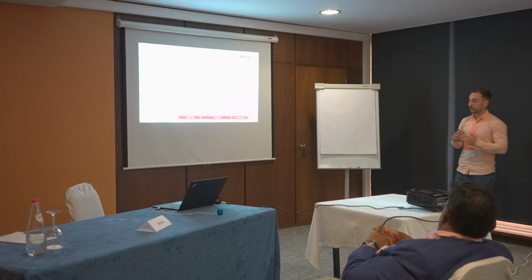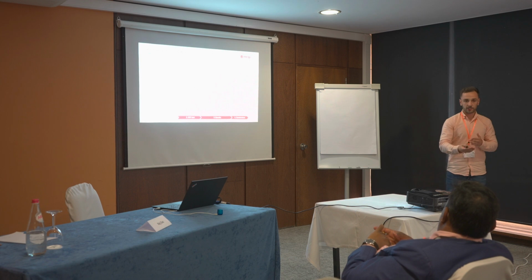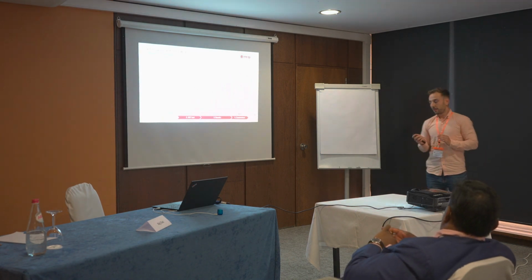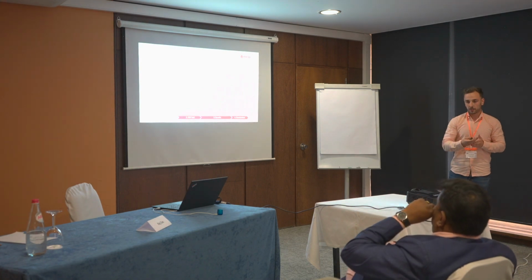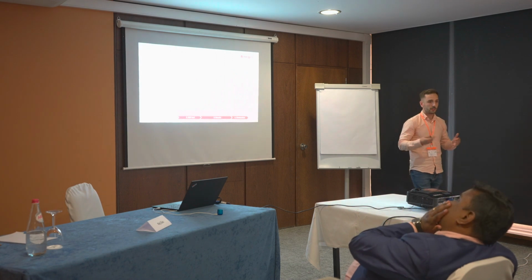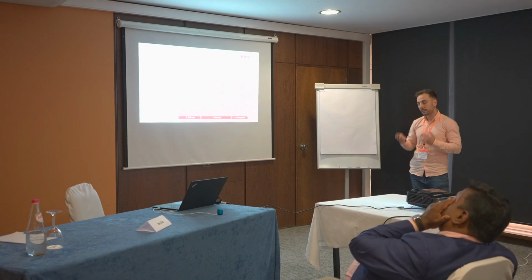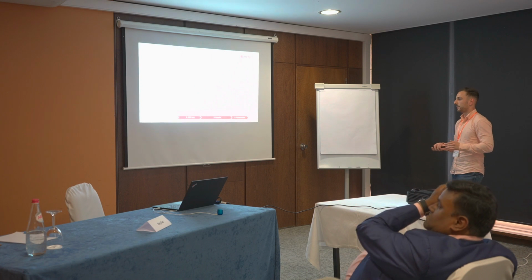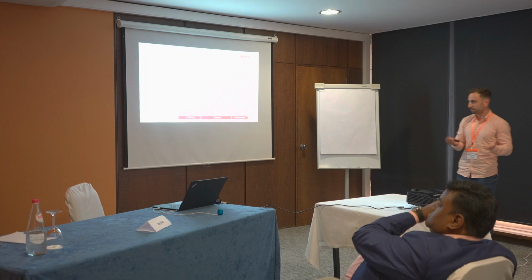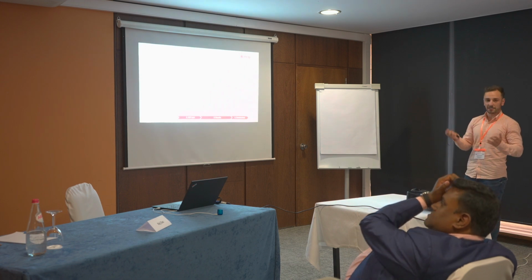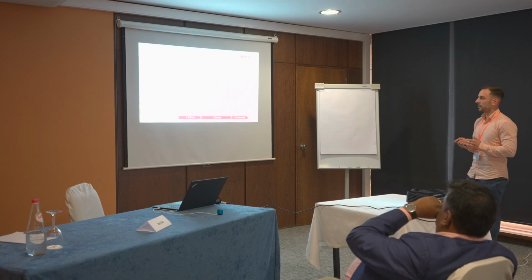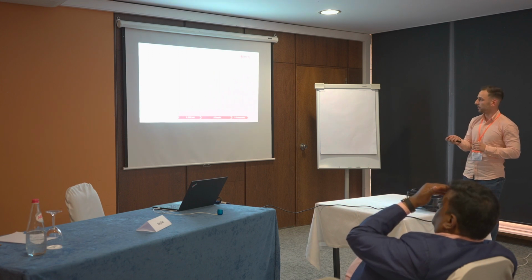In our case, we introduced the mannequin into the driver's seat, and actually it did not touch any component, although during the impact we observed that the dashboard would injure the driver. So we cannot validate this structure, basically. According to the norm, it is valid, but there is a but. For future work, there is a need to improve the position of the dashboard.